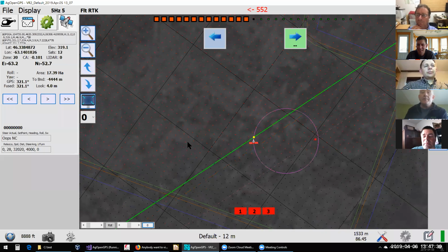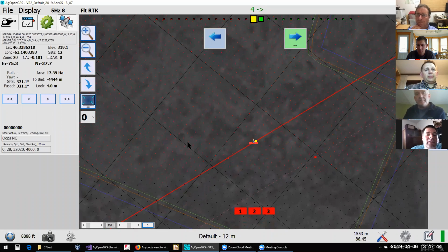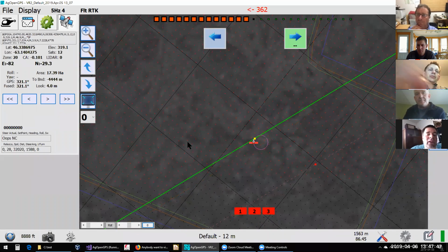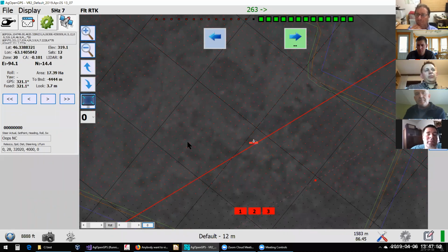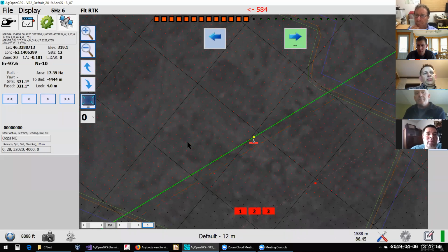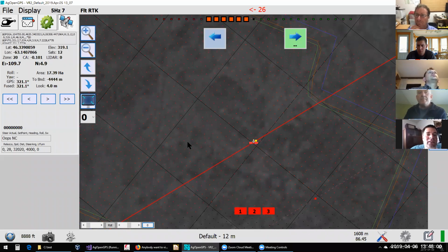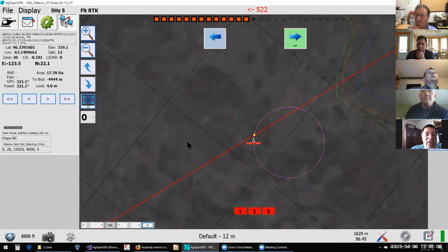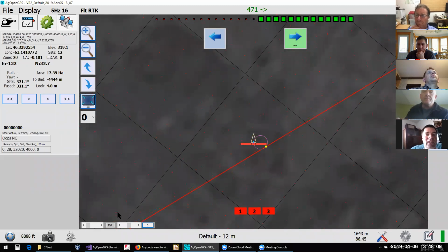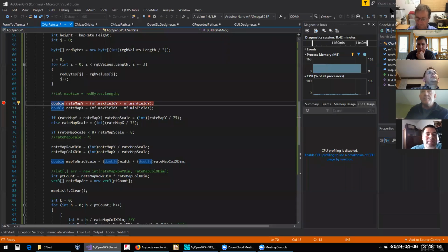When talking about the PGN, just a question. The serial ports all are separate, and if I send IMU data from a BNO chip via the GPS serial port, it is not recognized because the serial ports all are separate. So if I have the data on the GPS serial port, AgOpenGPS can't read it.